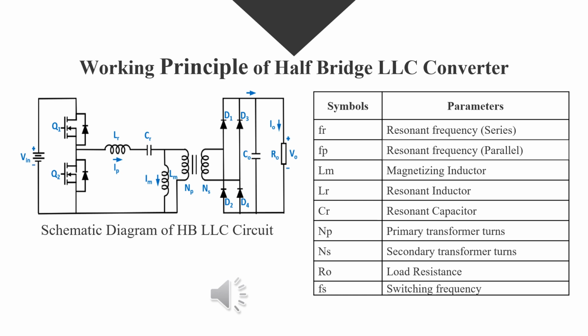On the converter's secondary side, the two diodes constitute a full wave rectifier to convert AC input to DC output and supply the load RL. The output capacitor smooths the rectified voltage and current. The rectifier network can be implemented as a full wave bridge or center tapped configuration with a capacitive output filter. The rectifiers can also be implemented with MOSFETs, forming synchronous rectification to reduce conduction losses, especially beneficial in low voltage and high current applications.